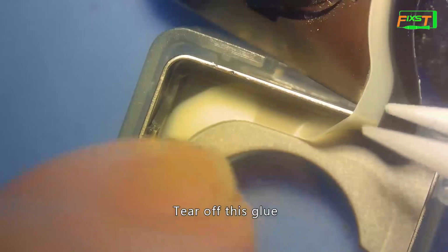Next, use the air gun. The hot air gun is a Quick 861DW. The temperature is 280 and the wind speed is 30. We are moving the glue like this. Don't blow it close.